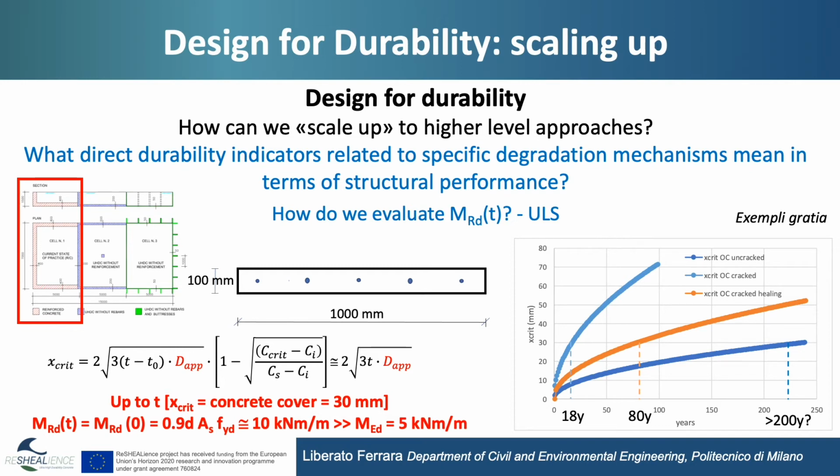We have calculated that we are under service condition at the cracking limit state. So we may not be sure that the cracks will not form. First of all, because we are exactly at the limit. Secondly, because we may have cracks due to shrinkage, due to settlements, due to deformation, and so on. So anyway, before the chloride arrive at a critical content at the cover, nothing happens.